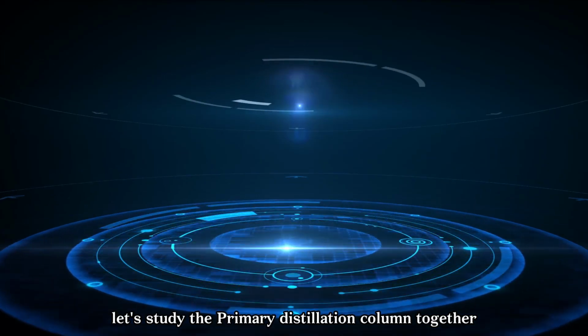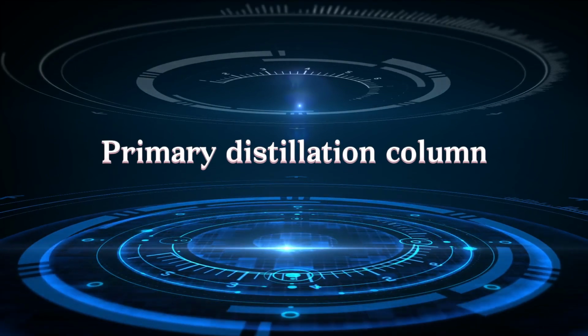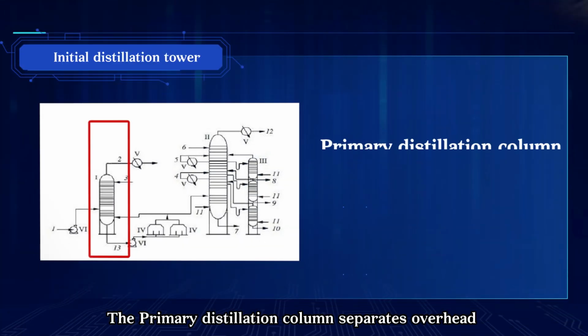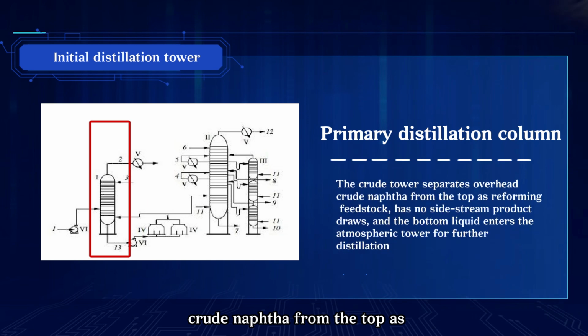First, let's study the primary distillation column together. The primary distillation column separates overhead crude naphtha from the top as reforming feedstock, has no side stream product draws, and the bottom liquid enters the atmospheric tower for further distillation.